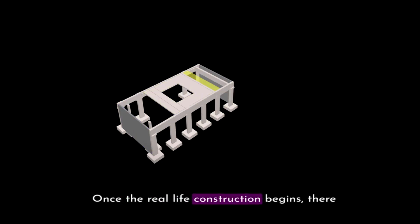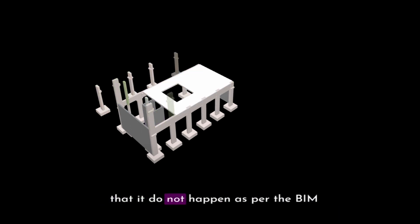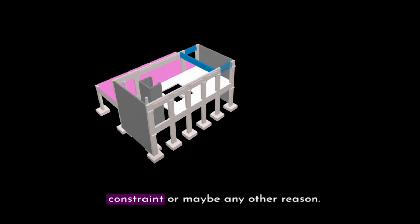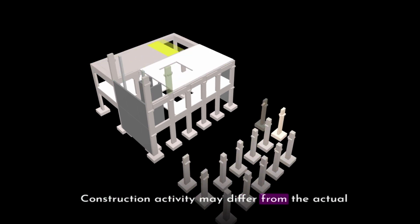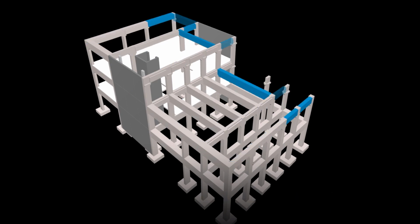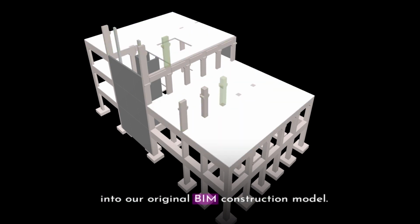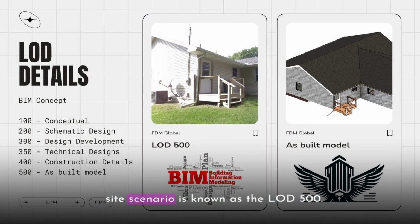Once real-life construction begins, there are multiple chances that construction does not happen as per the BIM LOD 400 model, due to some site constraint or maybe any other reason. Construction activity may differ from the actual LOD 400 model or the information given in it. These changes need to be modeled back into our original BIM construction model. The process of remodeling as per the actual site scenario is known as LOD 500 or as-built modeling.